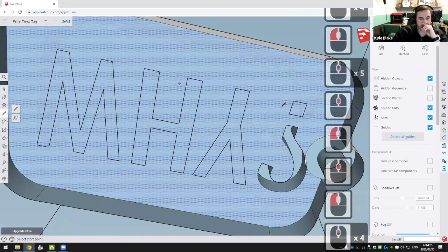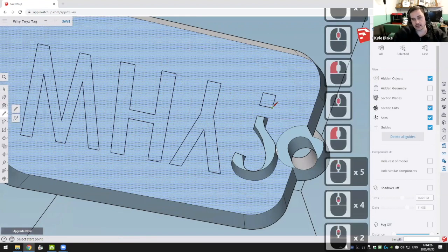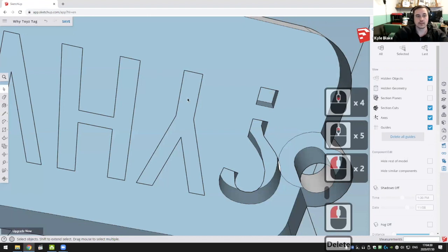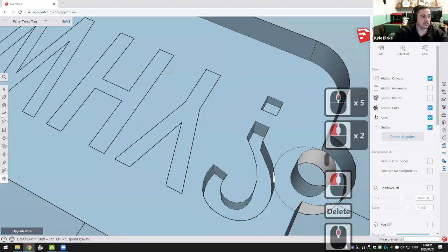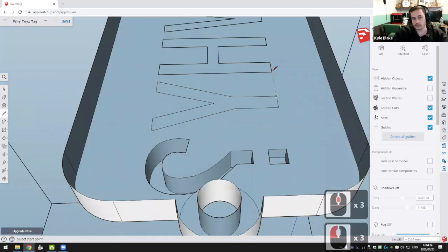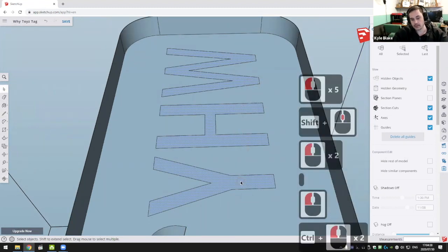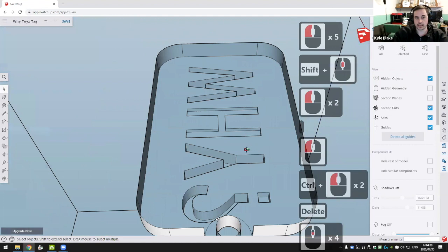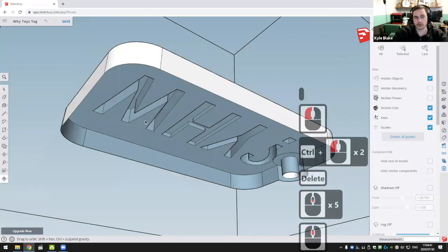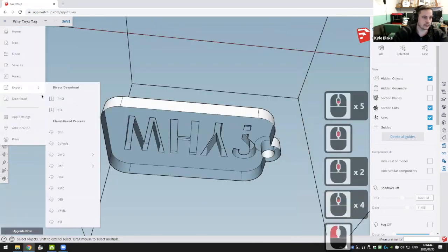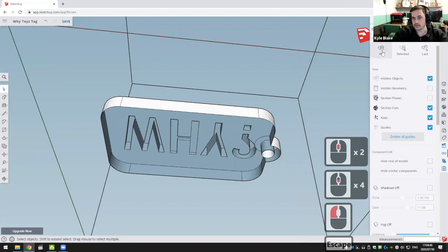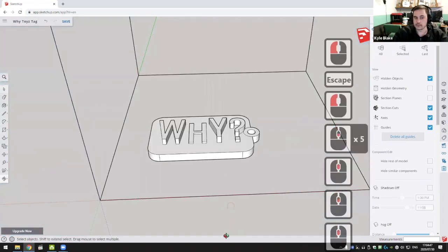So see that what's happened here is placing them down hasn't actually separated the faces out. So if you want, you can just go and draw on them again. They will go nice and thin, and then you can select them and delete them out. So you should get a nice hollow looking print like that, and then you can unhide your last face like that.